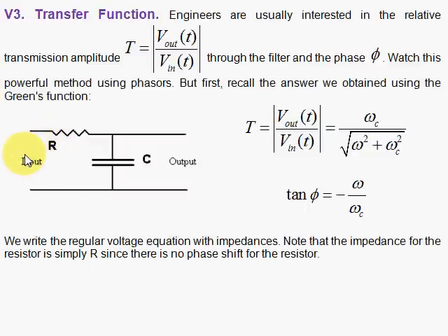Well, we do this with the phasor idea. Looking at the input voltage, it is going to be equal to the voltage across the resistor plus the voltage across the capacitor. You can think of that as a voltage of input minus the drop here, minus the drop there, getting you back to ground, has to be equal to 0, making that loop. And then by bringing the voltage drops for the resistor and capacitor to the other side, you have the voltage of input given by the sum of these two voltages. The output is only the voltage across the capacitor. That's what we're tapping off of.